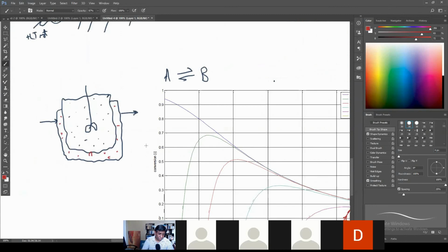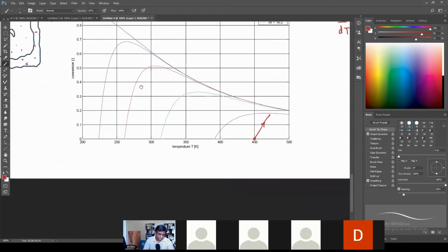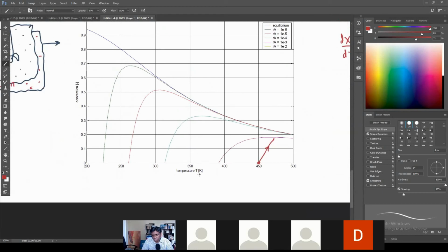Now, what we are trying to do in this batch reactor is maintain the temperature in the reactor such that we achieve the maximum rate always. So we want to achieve a high reaction rate in this reactor. And number one, we need to understand, what is a high rate then? Well, maybe even before that, if you draw this adiabat, we can see the system left to its own devices can only do this, right?